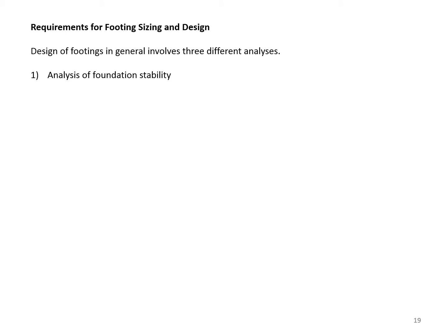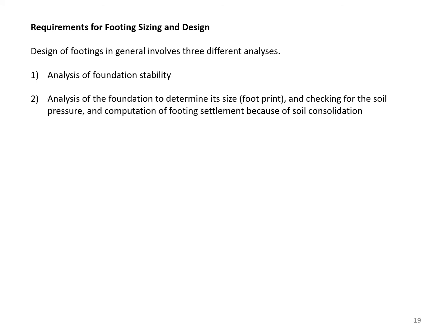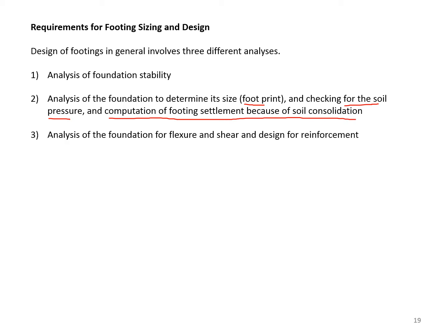Requirements for footing sizing and design. Design of footings in general involves three different analyses. Analysis of foundation stability, analysis of the foundation to determine its size, in other words, the footprint, and checking for the soil pressure, and computation of the footing settlement because of soil consolidation. And analysis of foundation for flexure and shear and design for reinforcement.